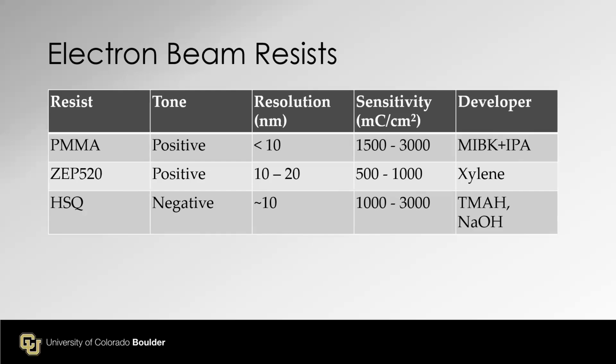ZEP 520, also a positive resist. Resolution is not as good as PMMA, but sensitivity is better. The developer is a solvent. HSQ, I would say the most famous negative tone electron beam resist. Resolution good, sensitivity not so great. The developer is an aqueous alkaline solution.